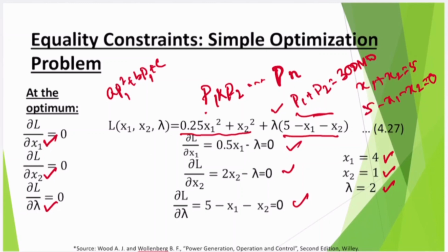Okay, so you have cost characteristics of the power plant: to generate P amount of power, how much money you have to spend. So my objective function will now be the summation of the cost functions plus lambda times the constraint, and that will help me understand what P1 and P2 are. Once the objective function and the constraints are known to me, I can easily calculate the value of power output of each and every power plant. And that's why it is important for you to understand simple optimization with equality constraint, with multiple variables.